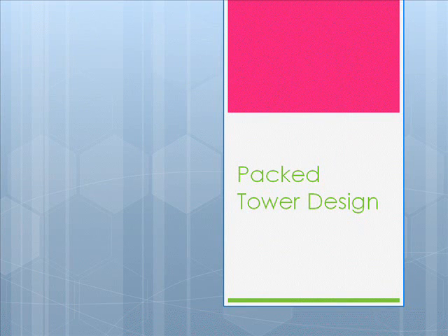One of the most extensively used and rapidly developing equipment in gas absorption are packed towers. A packed tower is essentially a piece of pipe set on its end and filled with inert material or tower packing. It operates in counter-current flow, where the liquid enters the system through the top and wets the surfaces of the packing, and the gas stream, mixed with the effluent, enters the bottom. Upon contact of the liquid and gas streams, the components of the effluent can be absorbed into the liquid.